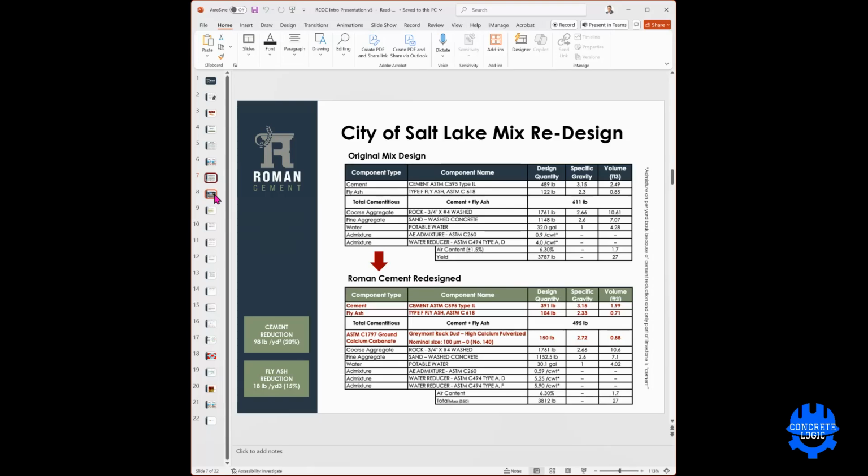Well, the limestone that we added was added at a silo at the ready mix plant. So it was definitely added, just like the fly ash would be added at the batch plant. The cement was in one silo, the fly ash was in the second silo, and the limestone was in the third silo. And that's been one of the impediments, installing new silos at a batch plant to utilize this third material, which we can purchase in large quantities and have it shipped to the plant.